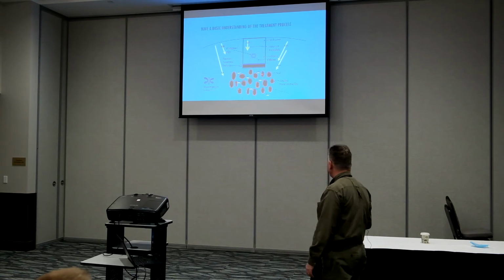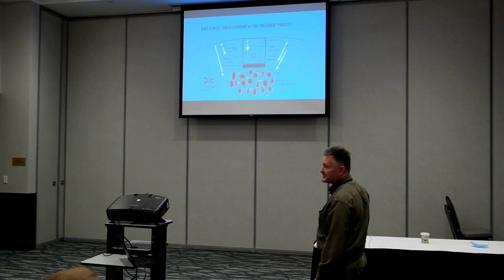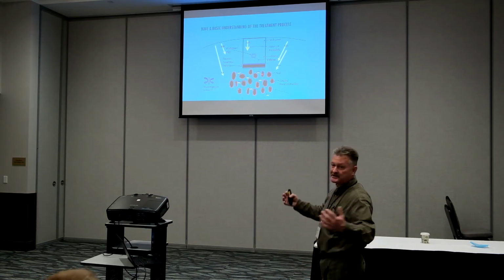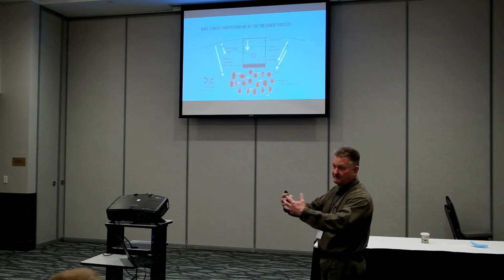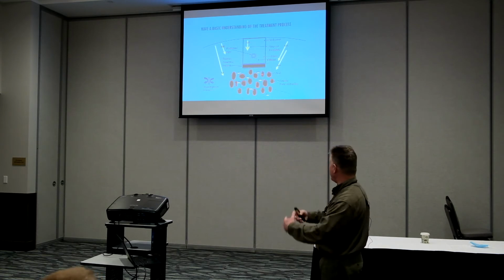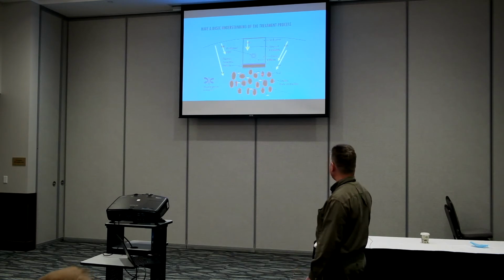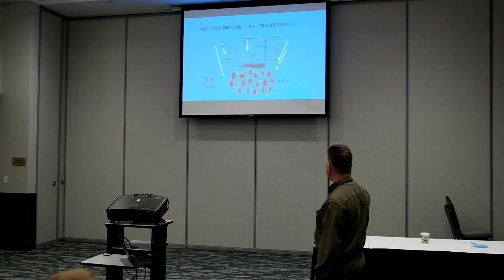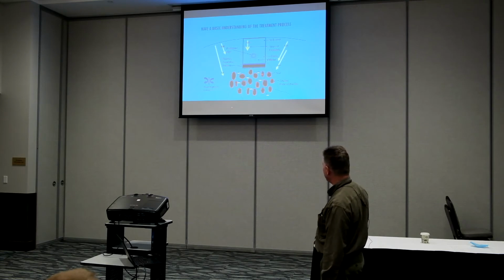So again, the main thing is we want to make sure the pore spaces underneath our field are open so we get a lot of gas transmission, primarily the breathing byproducts of the bacteria, and oxygen transfer to occur. In trenches, that has a shorter duration versus, say, a bed, where this entire area is biomatted. We have to come a long ways for that oxygen to come through.